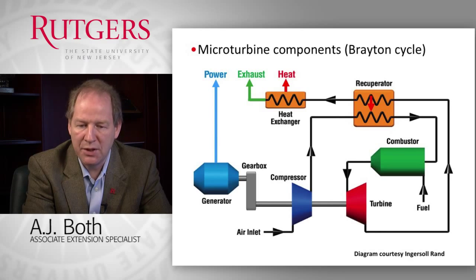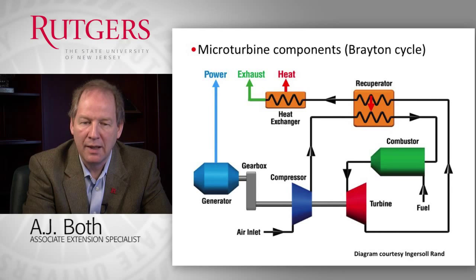The exhaust gases produced by the combustion process are collected after they drive the turbine, are run through the recuperator to try to preheat the compressed incoming air, and then run through a second heat exchanger to heat up, for example, hot water that you can then use to help heat a greenhouse operation before the remaining exhaust gases are then expelled to the outside environment.